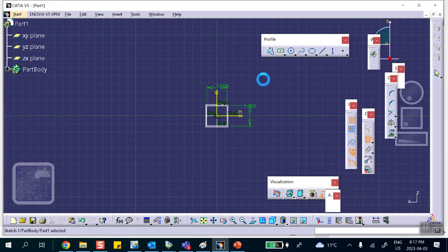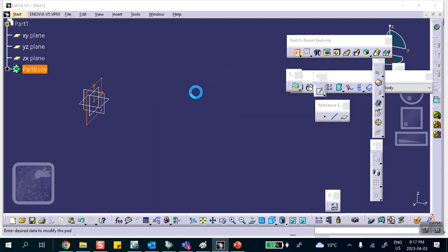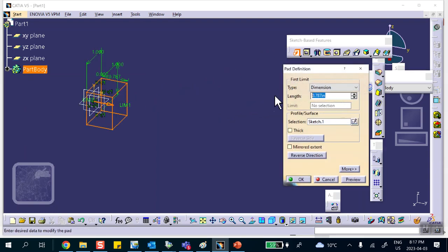Exit. And by the way, we are not using any symmetries in problems which involve the eigen frequency or eigenvalue calculation or natural frequency calculation or buckling load. Remember, I suggested to you not to use any planes of symmetry unless you're absolutely sure that you're not making a mistake. So this one, I'm going to go 20 inches long,